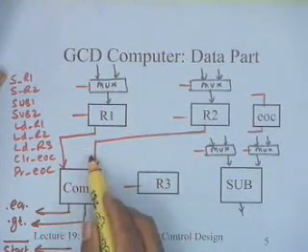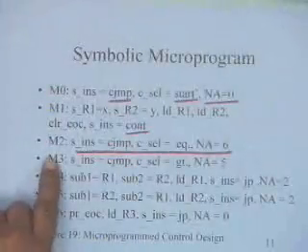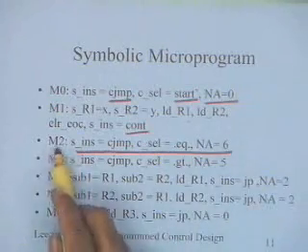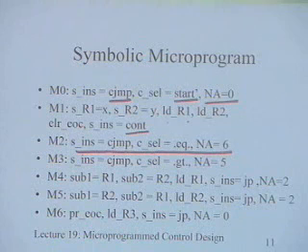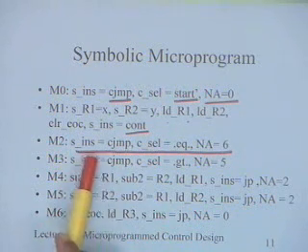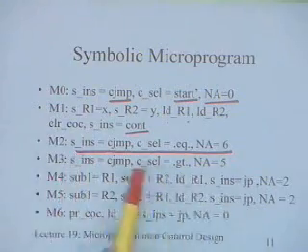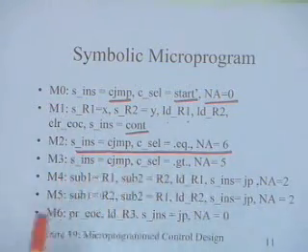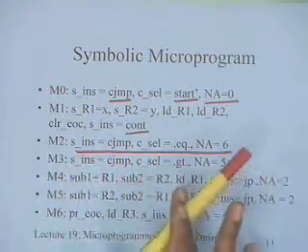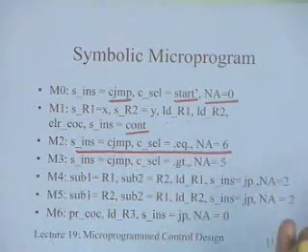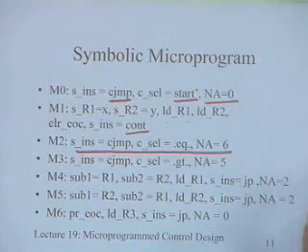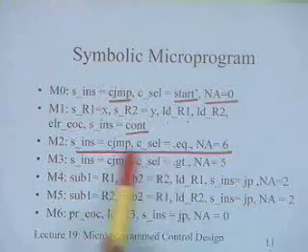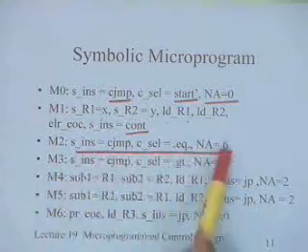If there had been a multiplexer here, I would have to choose that multiplexer to get the proper input to compare in M2 itself. That will happen at the beginning of the cycle, and by the end of the cycle, the comparator would be ready. So this timing model is something which you should keep in mind. This is a simple model that we follow unless otherwise mentioned: all actions take place at one edge, and all delays are less than or equal to the clock cycle delay. So I am performing this comparison.